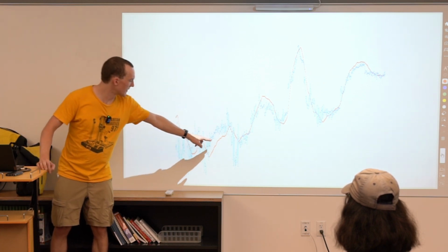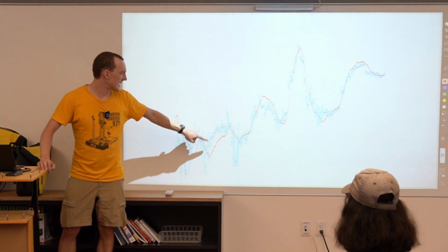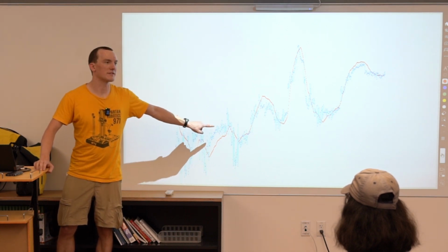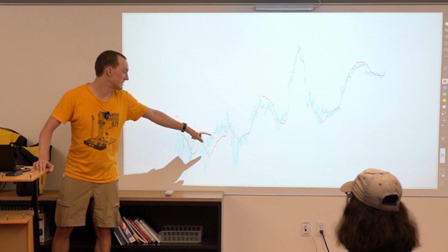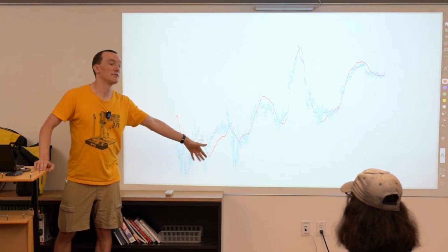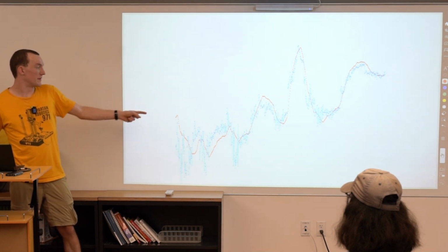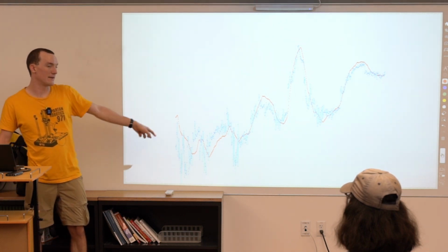I think there's some spots, like here, where our estimate is actually well below the speed of the encoder. That could be the wheel slipping, and so maybe our estimate is accounting for the wheel slipping, which is yet another category of error you have to deal with. So it's more than just smoothing out the jitter.